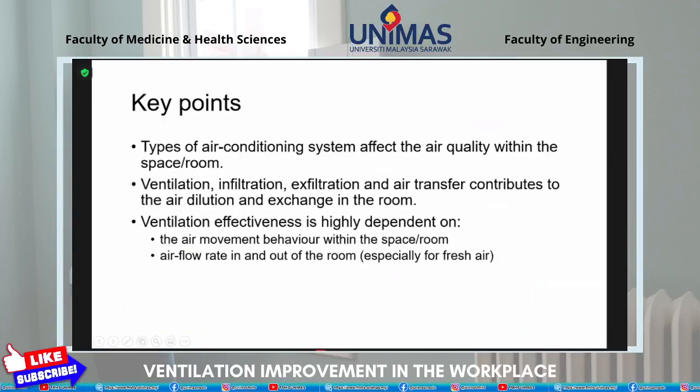Okay, so the key points for this part of the talk are that typically the air quality is really dependent on the air conditioning system that we have. And in order for us to have good dilution or exchange of air in the room, we should have the elements of ventilation, infiltration, exfiltration, and air transfer. The rate itself, the methods, the opening, the frequency, and so on.